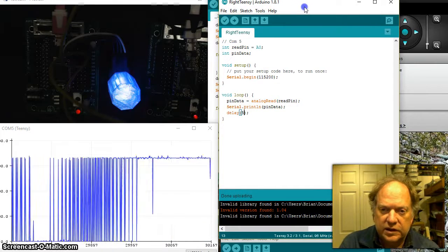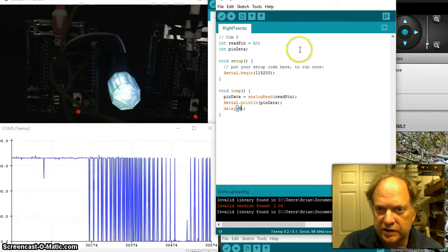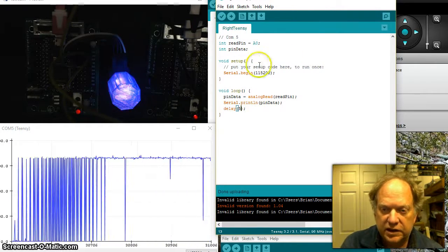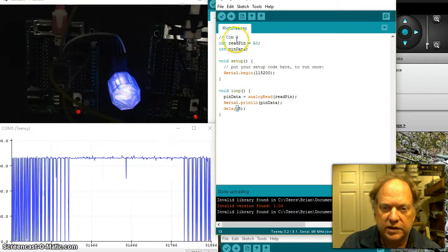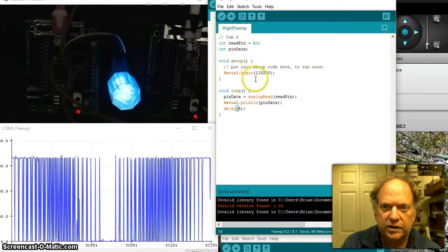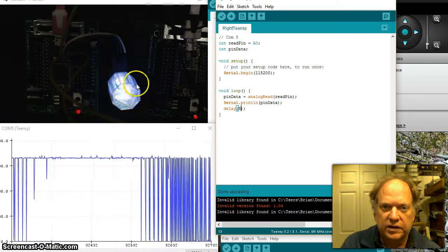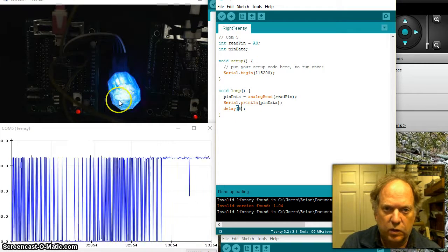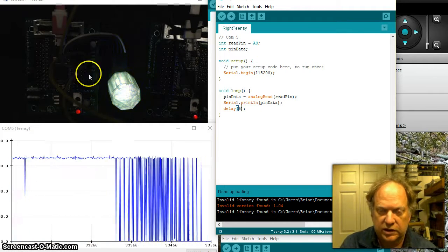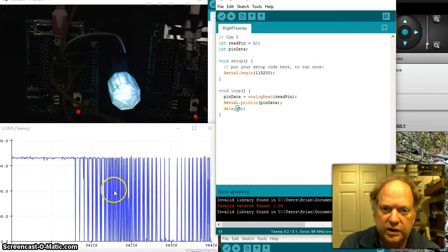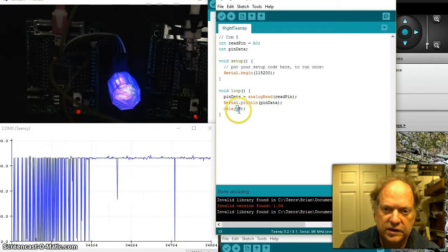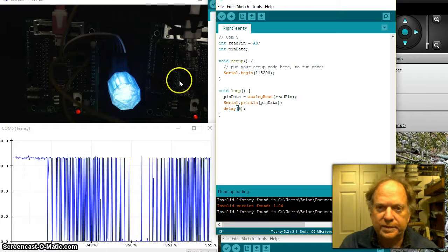Okay. So I did a few experiments because I actually don't know the answer. In this particular case, I've got it trimmed down to the bone. I'm taking a single analog read on pin 0, so I'm only reading the change in one LED. I'm reading the stimuli from one pin, directly outputting it, and then I'm delaying 5 milliseconds before I plot it.